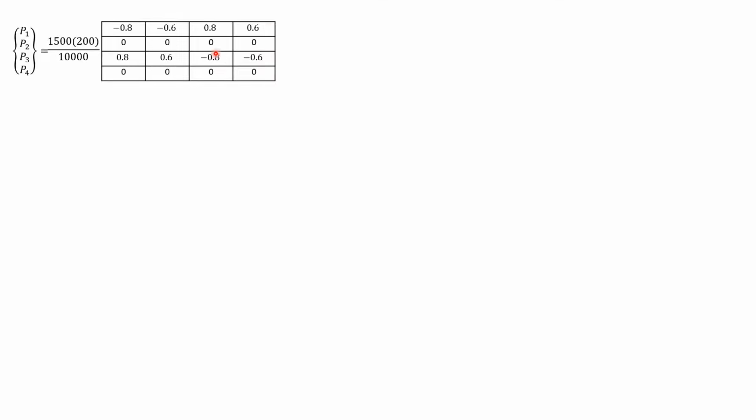Then the negatives of row 1 multiplied by the displacements 2.3287, negative 1.564, negative 7.4037, then U4 is 0. Then plus the fixed end forces, 300 and negative 300, remember, for member 1, due to temperature and fabrication error. And you'll get here 94.5744 and negative 94.5744. So member 1 is in compression.